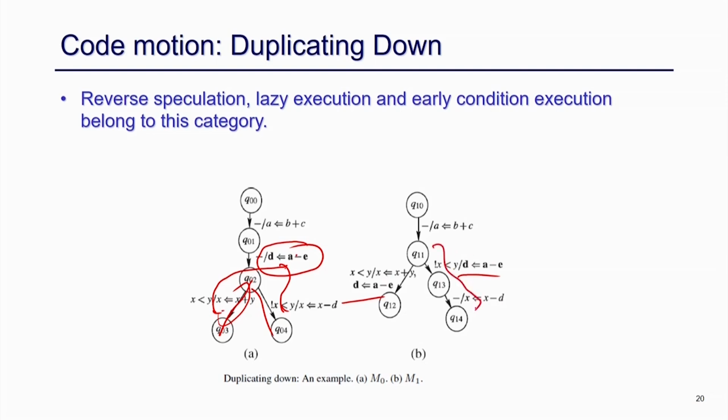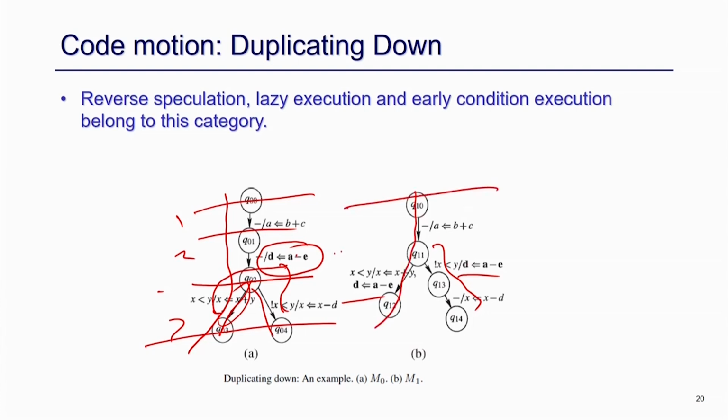So, the advantage is this: if the behavior is executing through this branch, then I need 1 cycle, 2 cycles and 3 cycles, so I need 3 cycles to execute the behavior. But here, if it is happening through this branch, I need 1 cycle and another cycle. So, I am saving 1 cycle in conditional execution. But whenever the execution happens through the other branch, I still need 3 cycles, because I have to do this in there.